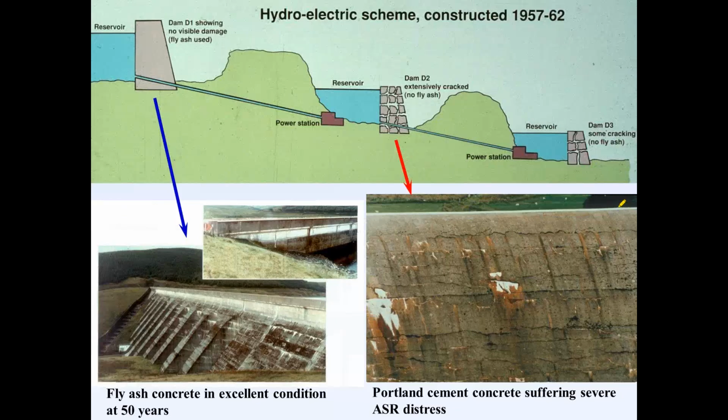The Dinas Dam shows very extensive damage due to alkali silica reaction in the form of very, very severe cracking. The dam's growing at somewhere in the order of 5 millimeters a year upstream because it's an arch dam. Upstream, they constructed using the same aggregate, cement with similar alkali content.